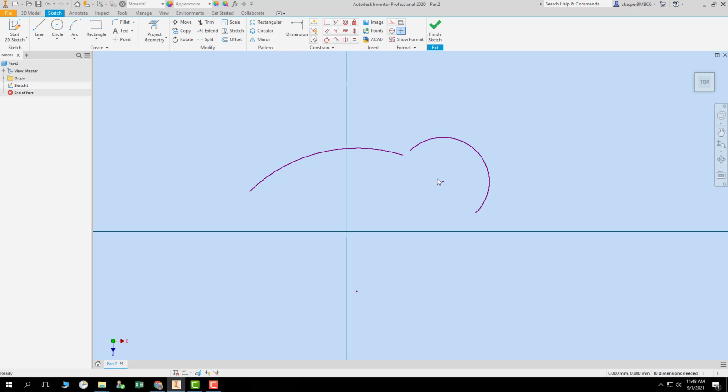I'm repeating that left click, right click combination because even I forget to do that. And it will throw you for a loop when you have them constrained, and you just right click on it and, oh, well, it worked that time. But sometimes it doesn't. Yeah, like right there, it didn't. That's because I didn't left click first. So I'll left click on it, then I'll right click on it, and there it is, delete. Okay.